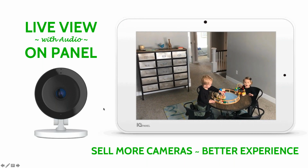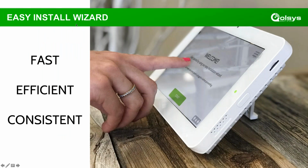So pretty cool. And then we also added this new install wizard. This is exciting. On the panel from the advanced settings menu, you can access this install wizard. Basically this wizard takes you through every step of the panel. It takes you through connecting to Wi-Fi and connecting your cell unit, getting it talking to alarm.com, updating the panel, installing your Z-Wave, adding user codes, installing the panel glass break detector, everything. It's a step-by-step install wizard that takes you from step one all the way through the full install. So we're excited about this.